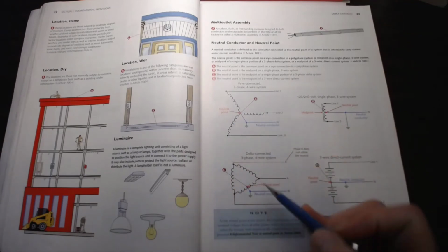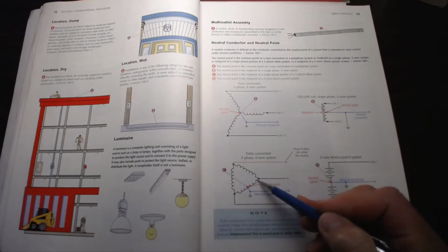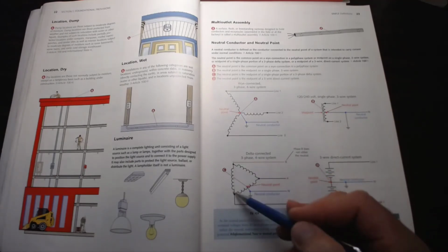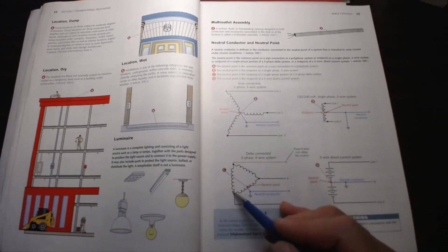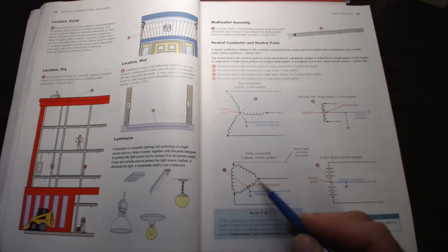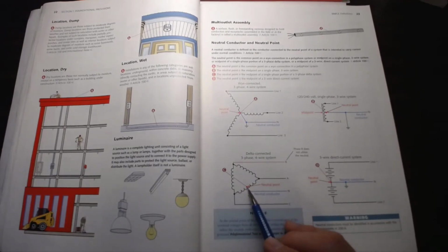It looks like a Y. For a delta connection, we have a triangle shape, which represents the delta symbol in Greek. So that's how it gets its name, but it's 3 windings connected with the 3 points together. And then when you have a 3-phase 4-wire system, you have a center point tap that is giving you that neutral tap point. So in this case, from C to neutral would be 120. From A to neutral would be 120 because it's half of this transformer winding, but the whole winding is 240.